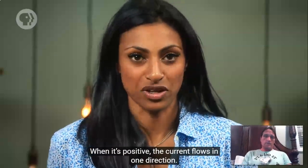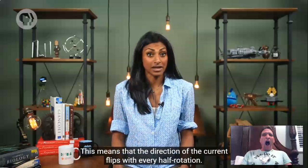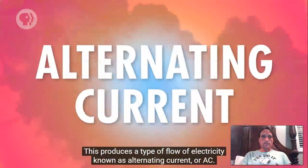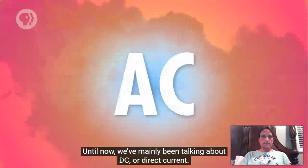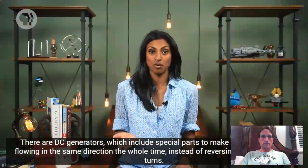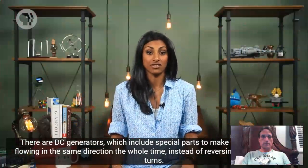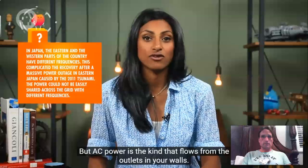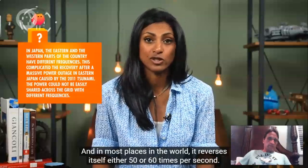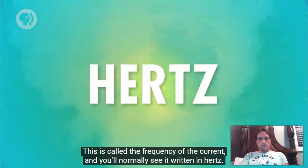When it's positive, the current flows in one direction. When it's negative, it flows in the other. This means that the direction of the current flips with every half rotation. This produces a type of flow of electricity known as alternating current, or AC. And until now, we've mainly been talking about DC, or direct current. There are DC generators which include special parts to make the current keep flowing in the same direction the whole time, instead of reversing itself as the coil turns. But AC power is the kind that flows from the outlets in your walls. And in most places in the world, it reverses itself either 50 or 60 times per second. This is called the frequency of the current, and you'll normally see it written in hertz.